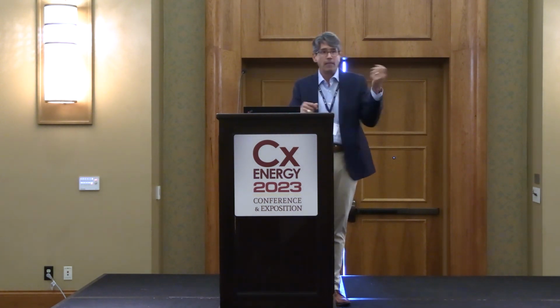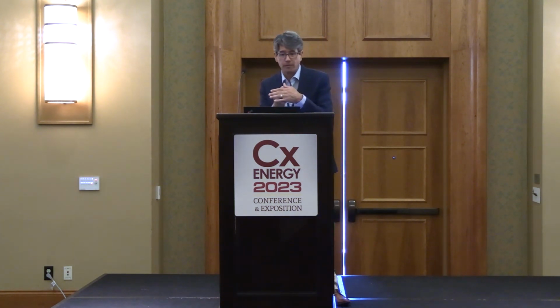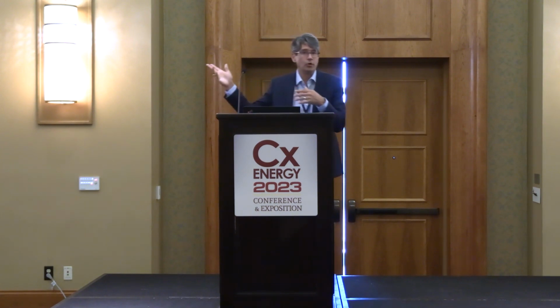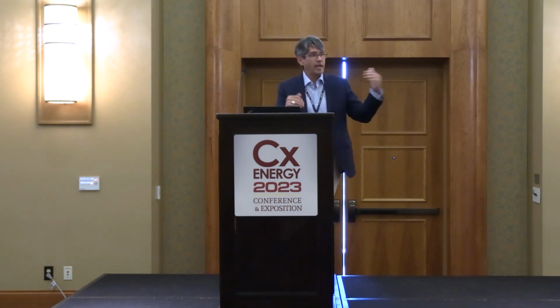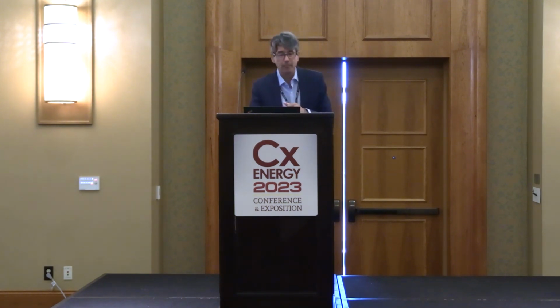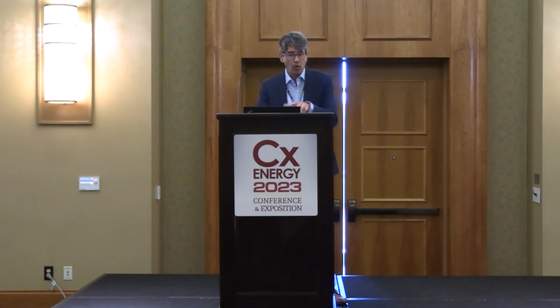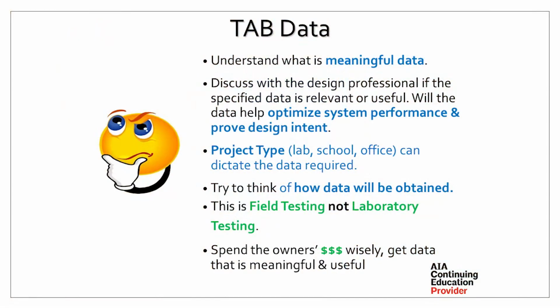Or you're out there looking at the installation. How is that installation shown? Control valve mounted right over the test ports of the balancing valve. How to use a flow hood, and better yet, even just making sure access to equipment's okay. Piping, electrical, all the utilities coming to it aren't blocking all the access doors and that kind of stuff. So all the different caveats of that can affect how the TAB company can actually get their work done, or even the commissioning company can get their work done. We'll hit some of these items further as we go through it.